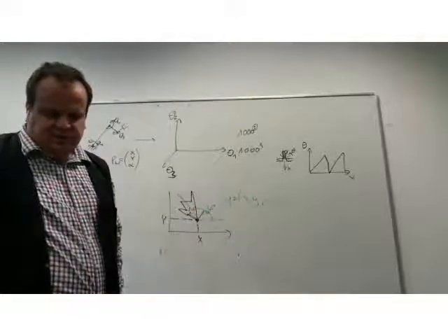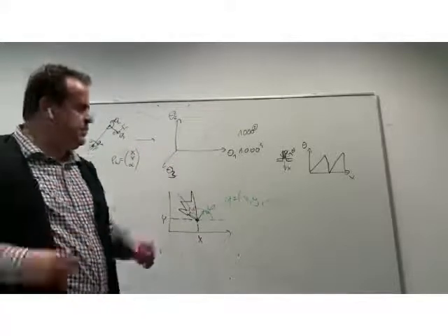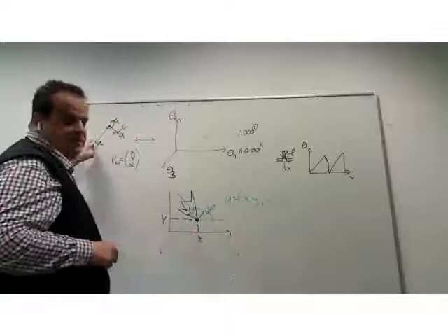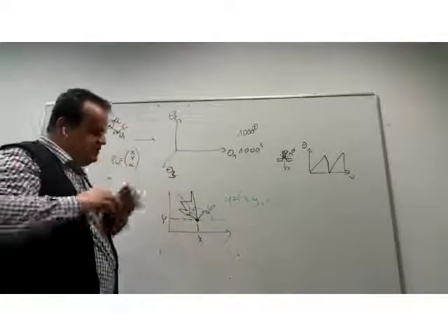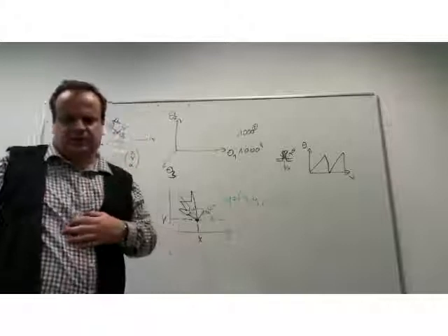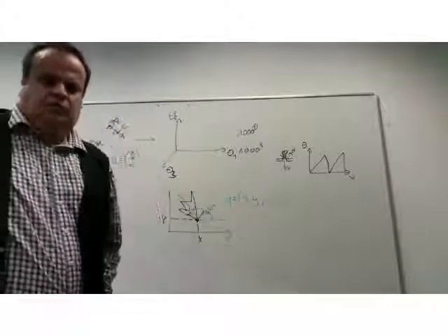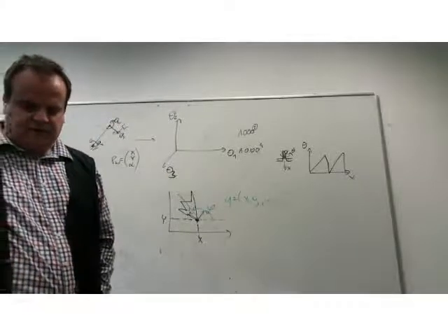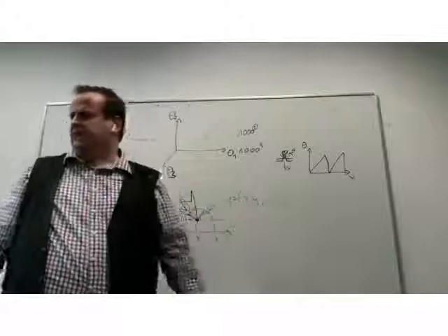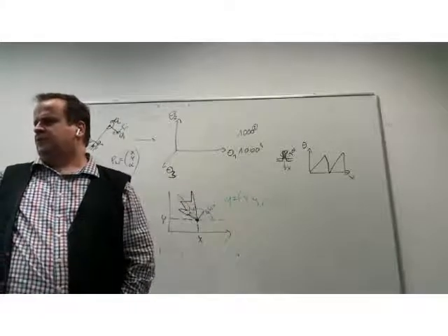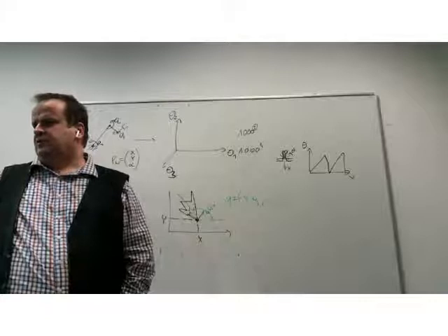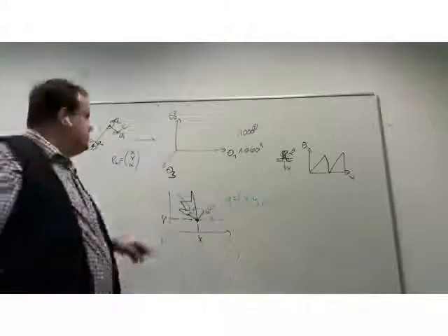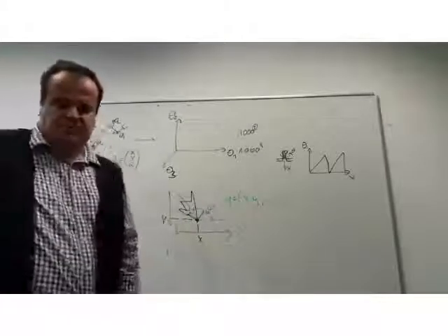So we have three different types of rotation, and we have one prismatic joint, which does not require a torque to be applied to the robot, but in this case, there needs to be a force generated by the actuator, maybe some pressure, to move this sliding cylinder in and out of this sliding element. So we have three rotational, revolving, and twisting joints on the robot, or a linear joint. And these are the only elements which create a motion, just because we assume a rigid robot, not a flexible robot.